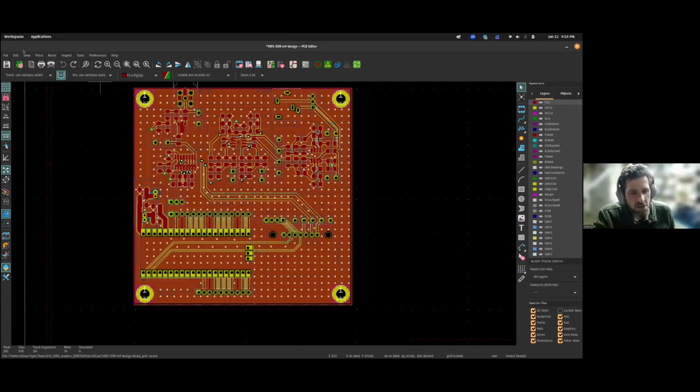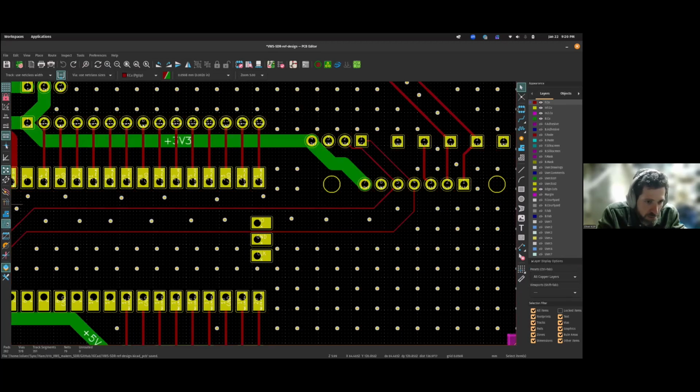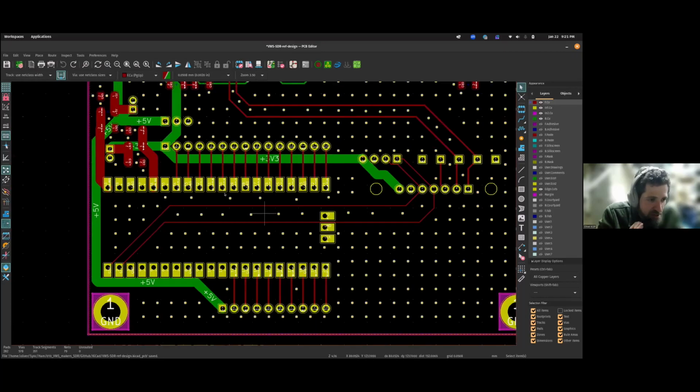Yeah, it's because of the way they're made. It's like 3 separate PCBs sandwiched together, and obviously copper layer touches copper layer, so that's a single layer, and so you end up with a 4-layer board. And what it allows you to do is have, so this is hard to see in this view. If I switch this to all copper, it's harder to turn off. Hit that button over there on the left, and that turned off the copper fill.